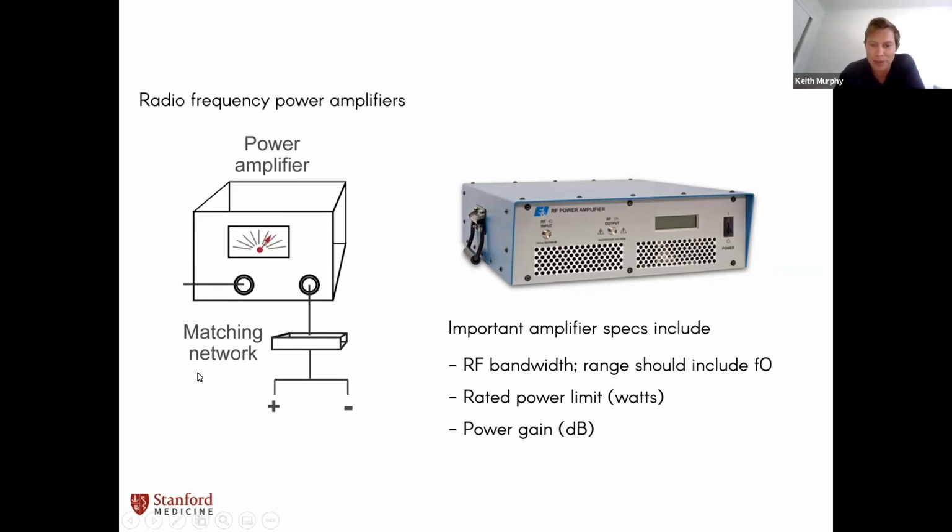Okay, and I will jump to the last bit of our basic setup here. This is not an essential requirement, but very often you'll want something called a matching network. As the name implies, we're trying to match something. Just like an ultrasound acoustic wave traveling through tissue, electrical alternating currents can travel through materials that have different electrical impedance, a willingness for that AC voltage to travel across as a wave.